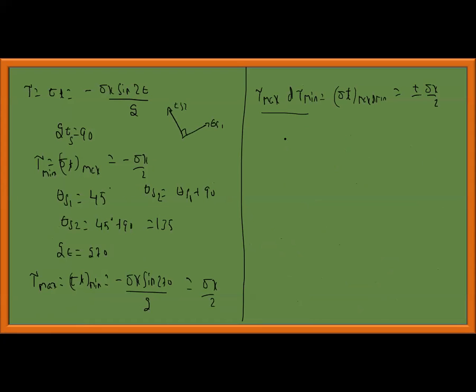This is called the Tresca theory. Tau max is given by the yield strength divided by 2. The maximum shear stress the body can withstand is half of the yield strength. This is the inference. That is why we are doing this, to know whether it will fail by tension or compression. From this we infer that only half of the load in axial loading can be withstood in shear stress.